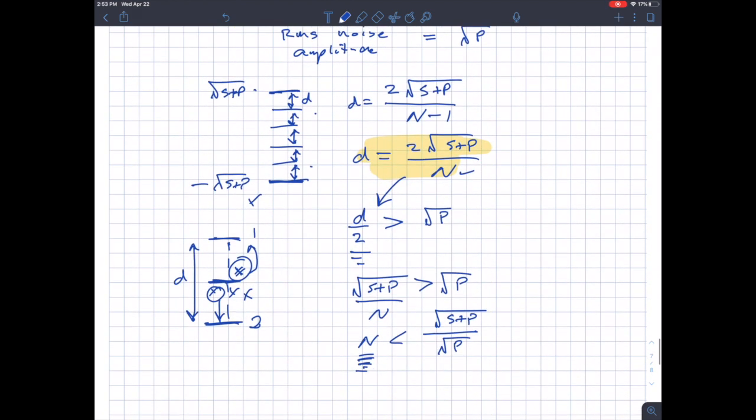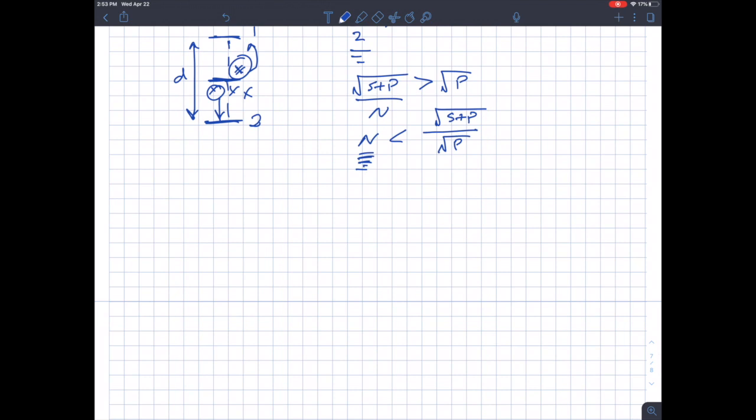And we also know that we have a certain number of symbols that we can send through the channel, based on the prior discussion about bandwidth. So here we go. What we know is that we have n levels. N levels implies log 2 of n bits. So I'm going to do n levels per channel use, or per message. That would be log 2 n bits per channel use.